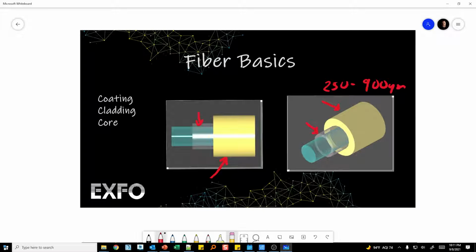The cladding is also optical glass. Some people like to display it like it's a whole separate layer, but it's really all melted together with the core. It's just on the outer edge of the actual fiber itself. This could be 100 microns, 200 microns, 150 microns, so there are different sizes depending on your cable. And then we have the fiber core itself. The size of this fiber is a little exaggerated. It looks more like multi-mode fiber here. But this is the actual portion of the fiber that the signal travels down largely. The core is that optical conduit that we use to transport our signals.